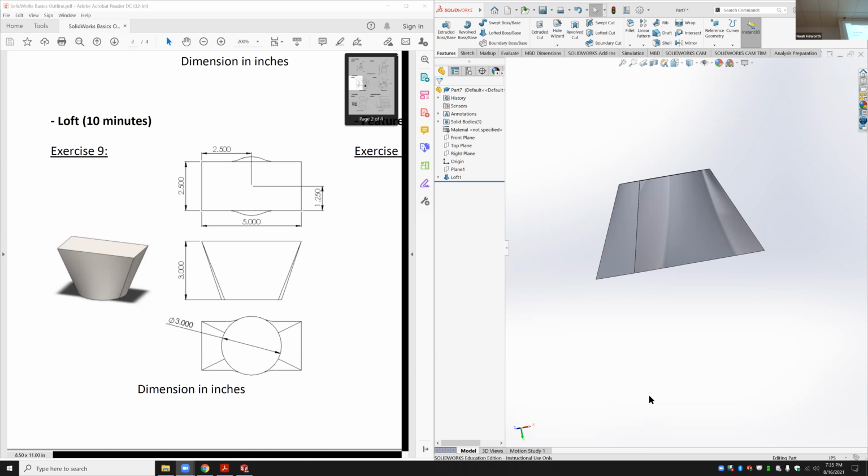Oh, this one. Okay. And then go through your planes, find out which plane you drew in, or if you just know, you can pick your plane. Yeah, the top one. And your offset distance, you know what your offset distance should be. Wouldn't it be the 3? Yeah, you want 3 inches. So it'd be 1.5, since it's the diameter.